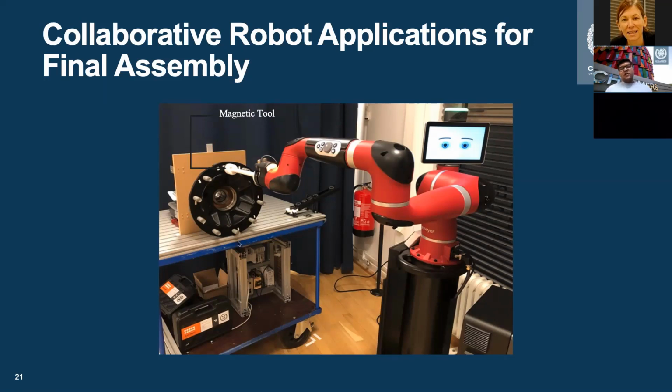The robot comes with what this company calls landmarks. They can be put anywhere in the assembly or anywhere in the workstation, and once it is programmed, the robot will first start looking for the landmarks, and based on the landmarks, it will calculate where its picking point is, and then take it to the placing point. So it has this inbuilt functionality, which gives us the flexibility of quickly moving it around in the assembly processes.